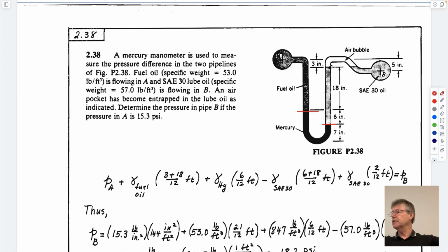What happens if you take a piece of hose pipe? If you want to put a foundation in and you want to move a level from left to 20 feet over here, you can do that quite well with a piece of Tygon tubing, because the water level in the tubing here and the water level in the tubing here will be at the same horizontal level. So think about taking a tube with an air gap at the top, put your thumb over the top, turn the tube upside down with your thumb over it. What's going to happen to that air pocket at the bottom? If the tube's large enough, it's going to travel up to the top of the tube, they'll join each other, and they'll sit as an air bubble. That's exactly what you have here. So the pressure, the level at this point here, if it's an air bubble in that tube, has to be the same on both sides, right? So that has to be at the same level. So that's the trick for this one. Tricky trick, but it's a trick nonetheless.